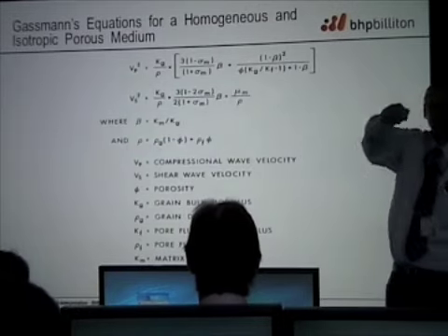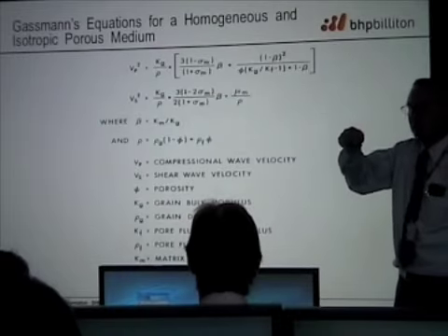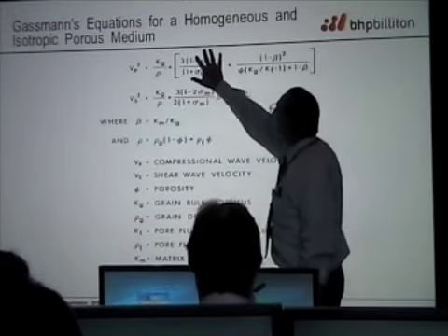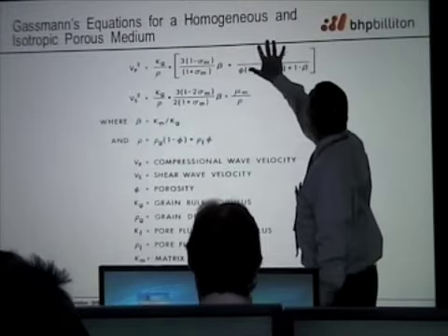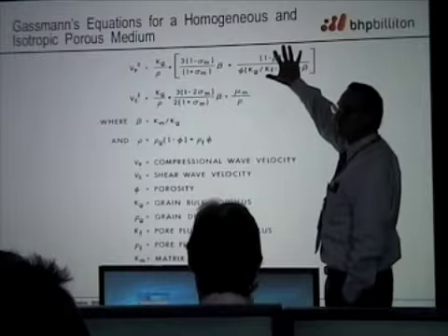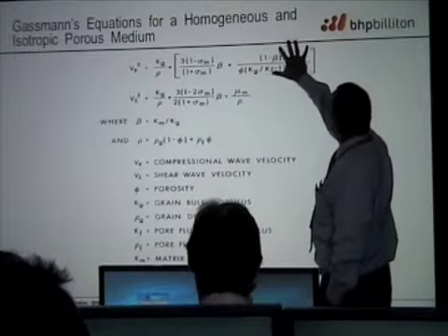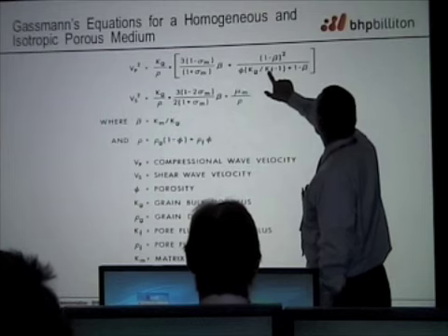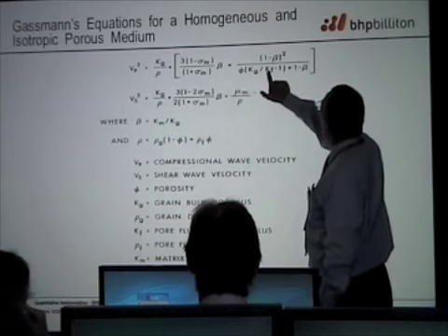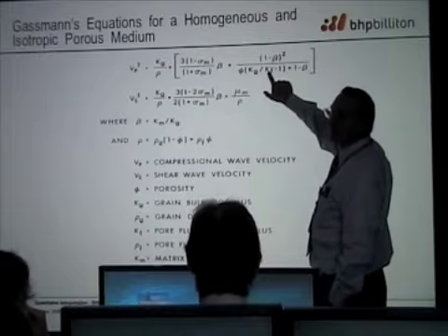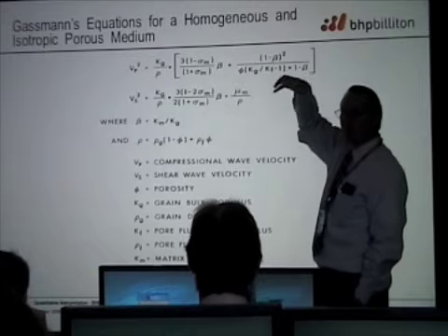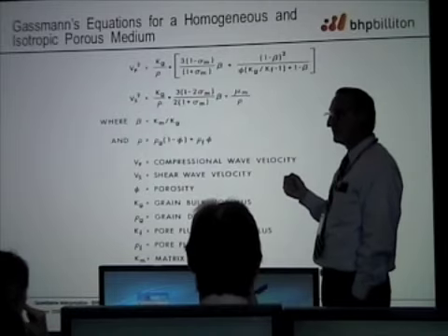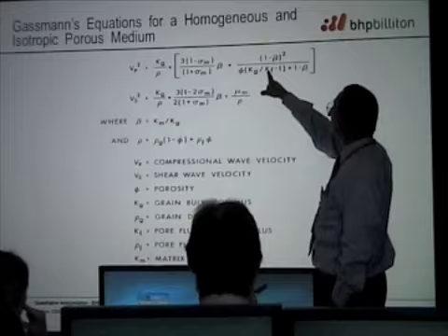Let's go to the other extreme. Let's think about the other end. Beta close to 0, what happens? This guy gets little, and this guy gets big. Then this thing can dominate. And look at what happens. This thing, Kg is always bigger than Kf, lots bigger. Remember I said 55,000 psi to squeeze that 1% for silicon dioxide, but only 4,000 psi for water?